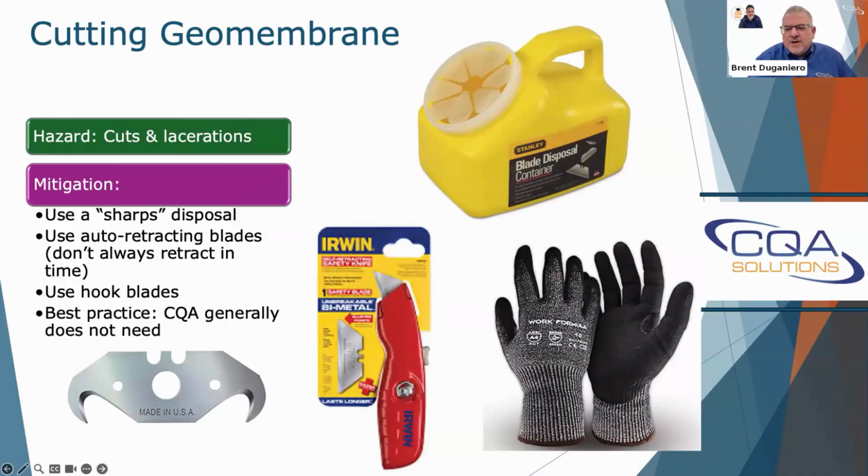If you are cutting the geomembrane, you want to make sure you're using a safety knife with an auto-retracting blade. But even with that, you still have to be careful, because it's only going to auto-retract if your thumb lets go of that trigger. So it's a safety tool, but it has to be operated properly. We also recommend you use hook blades. If you don't have a hook blade, your blade's going to slip and slide on the geomembrane, it's going to be difficult to get a good grip on the liner, and there's more tendency for your knife to swing. You should have cut-resistant gloves.